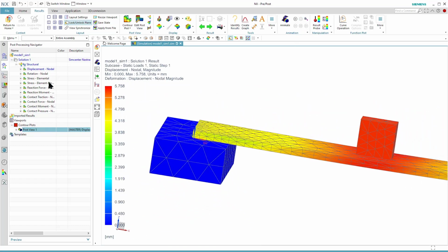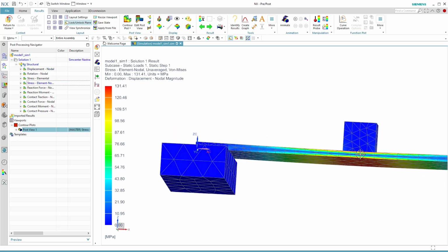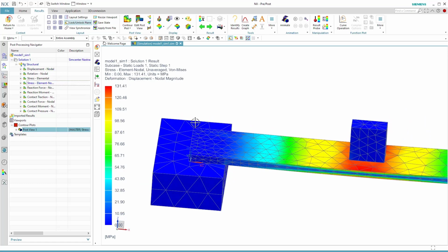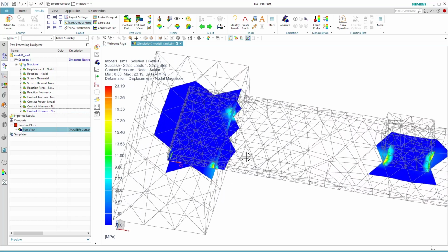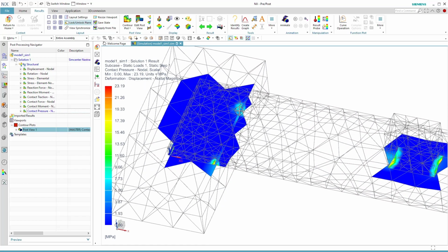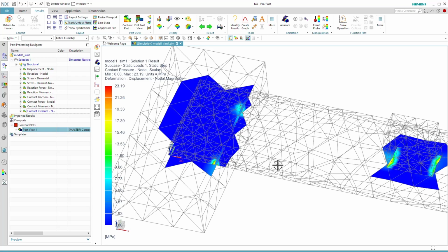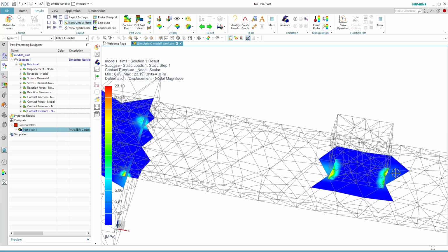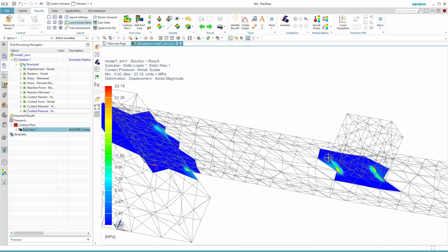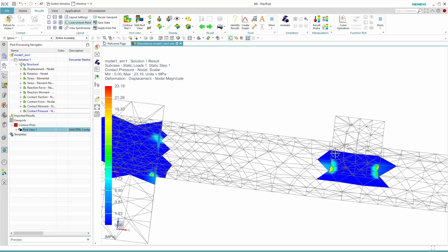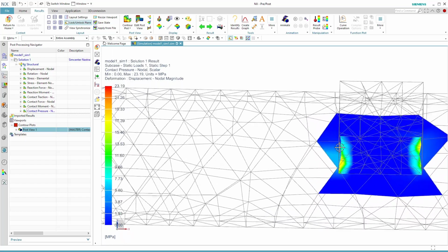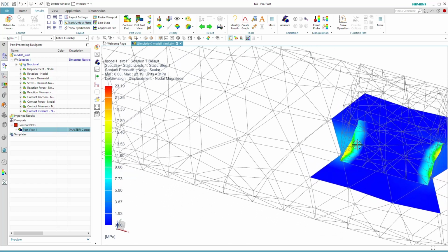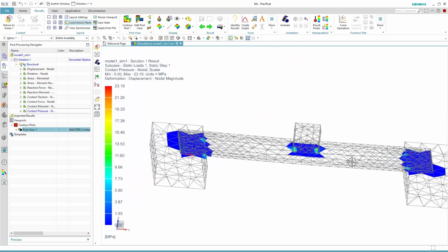What's also okay, that's the stress. We have typical here flexion, large stress, and you can look at the contact pressure levels, so you see what's happening in this contact pressure level, and you see here, or we can see it's a lot of pressure on the side of these cubes. That's the reality, but convergence is really bad because we have too large elements.